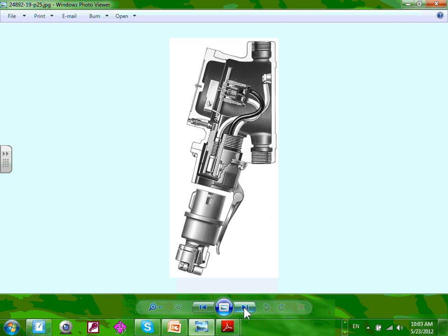That's also explosion-proof. The way they design them, guys, is that you have to interrupt the circuit before you unplug. You interrupt before you unplug. You can't unplug while energized, because that will spark, right? So first you interrupt it inside the explosion proof, and then you unplug it.